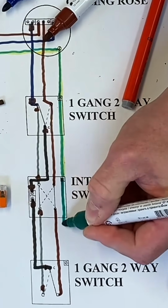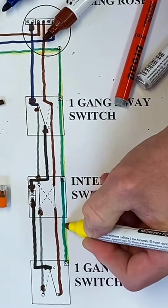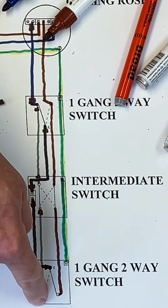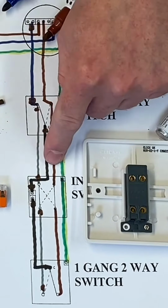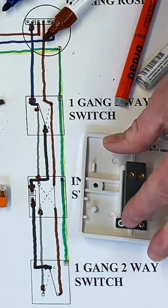Bring down our green and yellow cable, and again, just strike a little bit of yellow against it. So from the intermediate switch, we've come down now with another 3-core to our next 2-way. Within our intermediate switch, we've got a brown and grey in the top from one of the cables. The bottom, we've got a brown and grey from the other cable coming out the bottom.